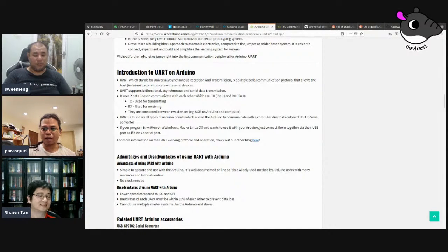And I guess you'd notice as well, Suimeng, right? Like many of the serial protocols, data protocols that you use with the sensors, they will always have a checksum at the end. They'll have a packet header and a checksum because that's just how serial works. You don't really know whether you've actually received it until you've received everything, and then you can confirm that you've received it correctly. Otherwise, you'll have to ask for it again or wait for the next packet.